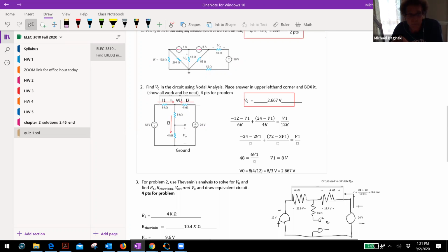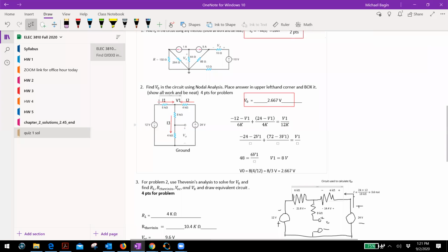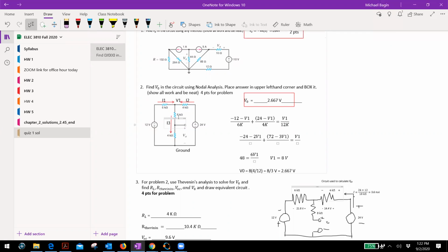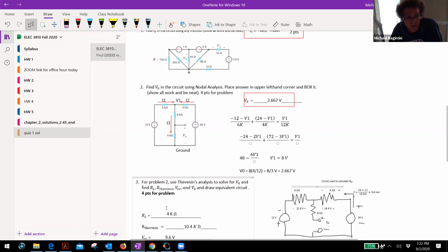Either way you do it, it comes out the same. It's 2.4 k ohms, okay? You follow me on that or not? Yes, I follow. All right, so that's just added to 8. So therefore, it would be 10.4K, right? Yep. All right, now if you have that, 10.4K, you understand the 4K is the load, right?